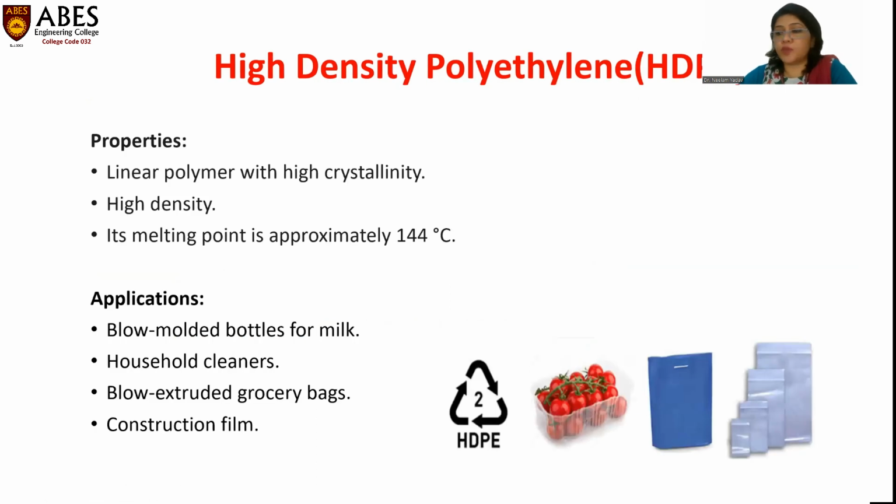Now the properties of high density polyethylene: these are linear polymers and show high crystallinity. The density is also very high and the melting point is approximately 144 degrees centigrade, which is higher than LDPE. Now the applications of high density polyethylene basically depend upon the preparation method used.